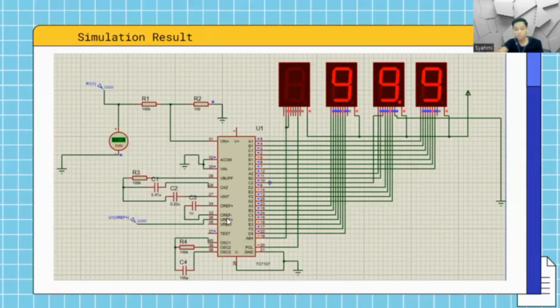The ADC used in ICL7107 is a dual slope type ADC. The power dissipation is under 100 milliwatt, and the display stability is quite high. Using the design guidelines provided in the data sheets, we created a simple 100 volt DC voltmeter, and it shows 3 digits with a 99.9 volt maximum. And the reference voltage of 100 millivolt is generated using 1.2 volt Zener and variable resistors from a voltage divider.